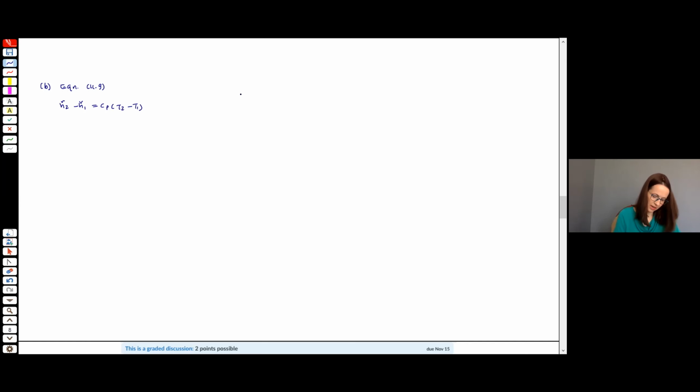Let's go ahead and calculate CP. It's equal to K times R over K minus 1, according to equation 11.14 that we just derived a couple of slides ago, or it's equal to K times CV. So let's use this one because we just calculated CV. When we do this, it gives us 1,004 joules per kilogram Kelvin.